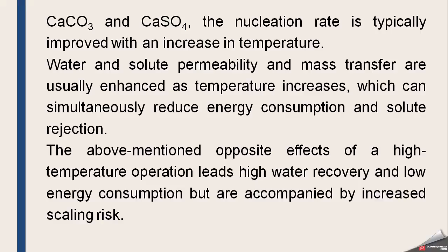By increasing the temperature, more energy is available, and more clean water is passed and less energy, less pressure is required for getting the product water in the RO, and this will help us reduce energy consumption and solute passage. More solute will be rejected because most of the salt will not pass through.